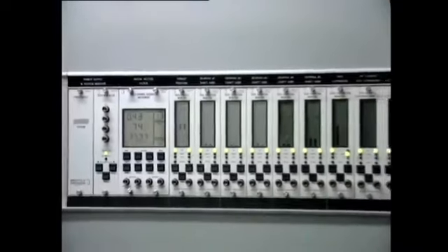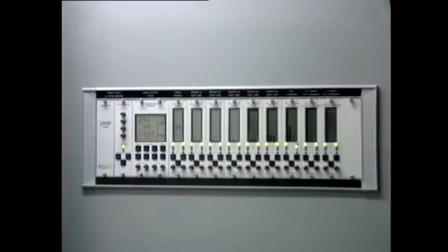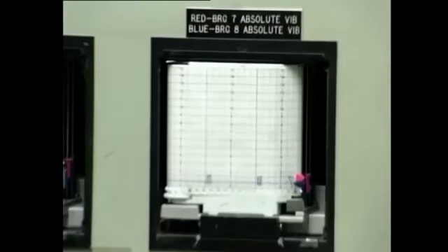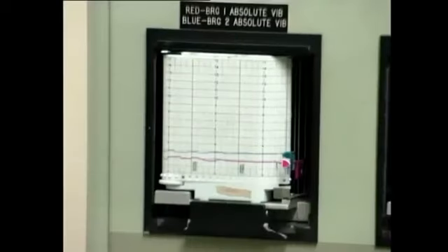It is important that the operator keep his eye on these reported levels of vibration. Any sudden change will certainly indicate the occurrence of a potential problem. For example, increased vibration on a generator bearing at a certain loading has been used to identify problems with the generator windings. Similarly, a temporary increase in turbine bearing vibration may be an indication that the operator is applying load too fast.